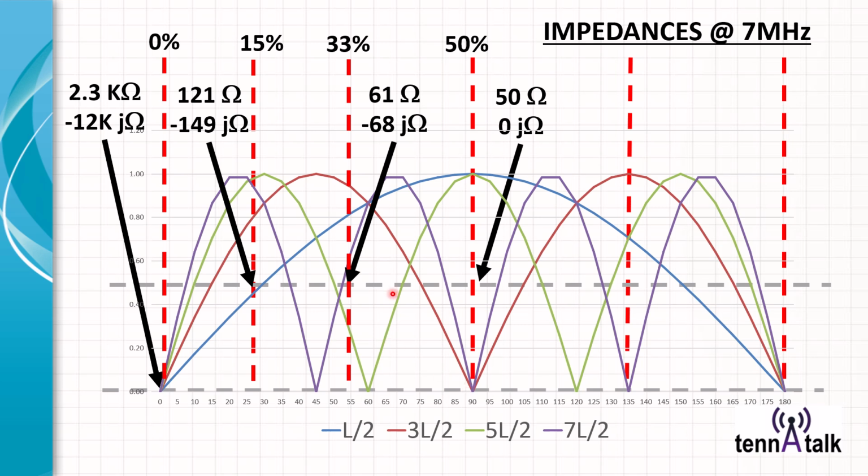But if we go to 15 meters, you see the green arcs. I have one of those 3 green arcs right here in the middle. And so that's why a 40-meter half-wave dipole fed in the middle can operate in 15 meters. And then 10 meters is the 4 purple arcs that you can see here.